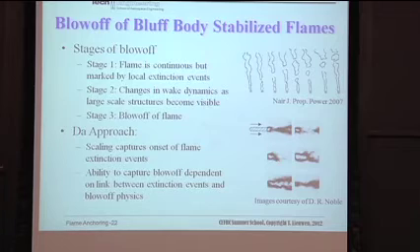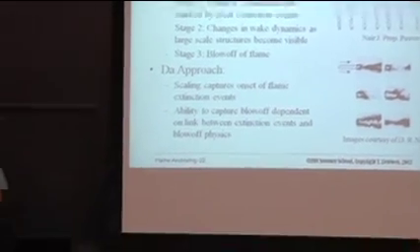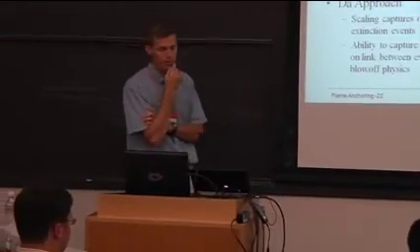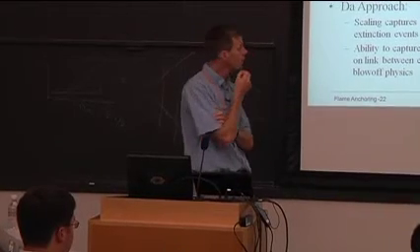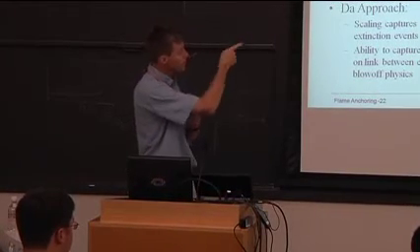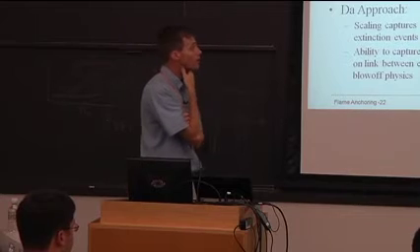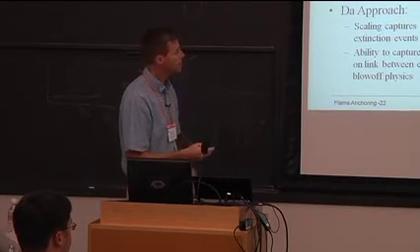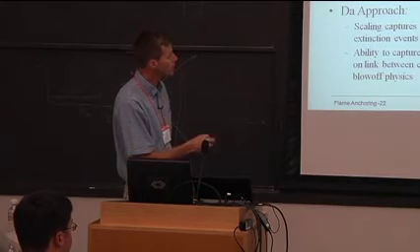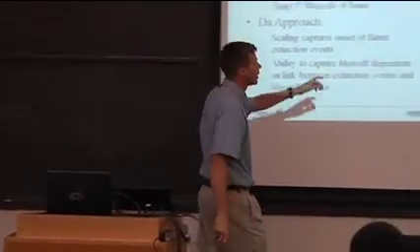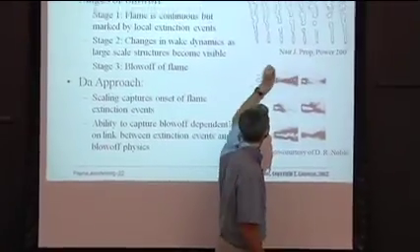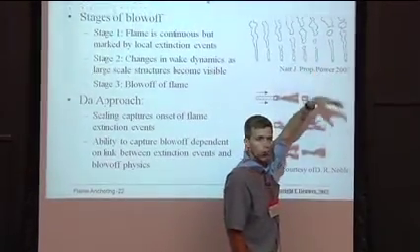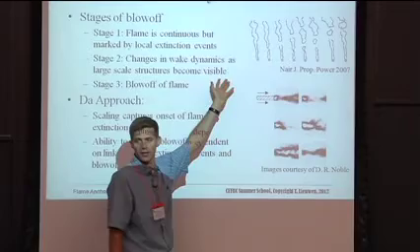And so what happens is that when you have recirculation stabilized flames, again, as I said, blow-off becomes a process. It's not an event. So let me explain what I mean by this. What I have here are a bunch of images of a bluff body stabilized flame where I'm close to blow-off, but the flame is not blown off yet. In fact, the flame will look like this perpetually. What you're basically looking at are different realizations of the flame. And you see these holes in the flame that are opening up, convecting downstream. The flame will sit like this forever.